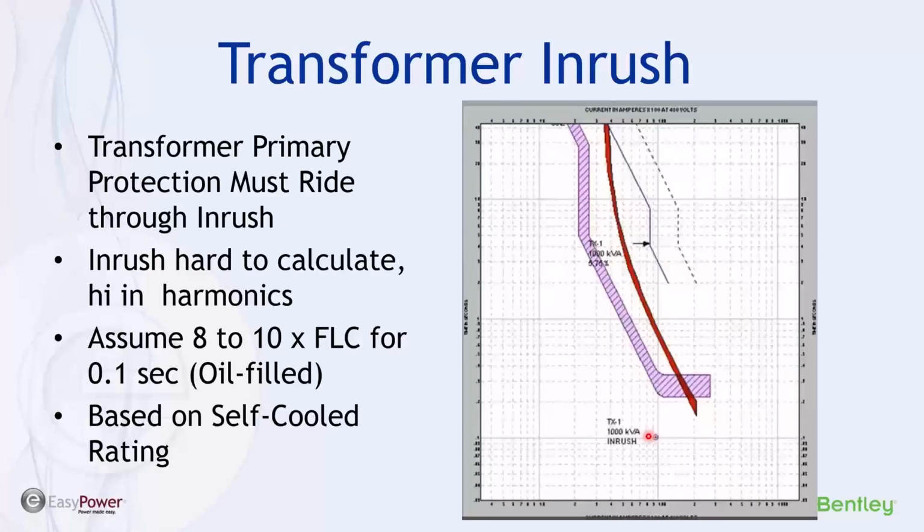Here's a good question from Jesus. Using the 450-3 chart, is it possible that we oversize protection as a result of the high arc flash values? So I believe what he's referring to is the ability to oversize or include additional capacity in the transformer so I can fall within the damage curves with my primary protection.